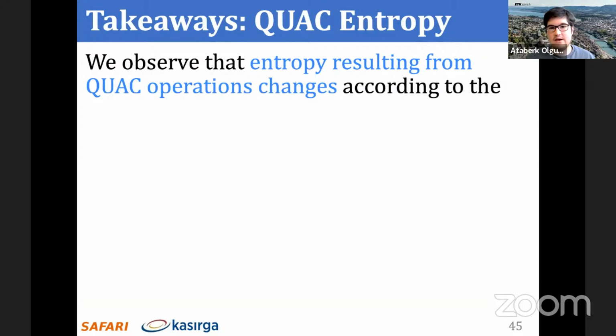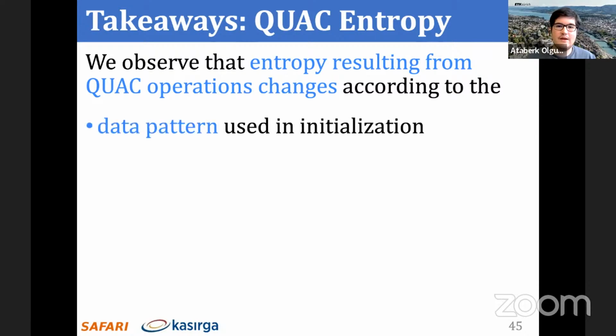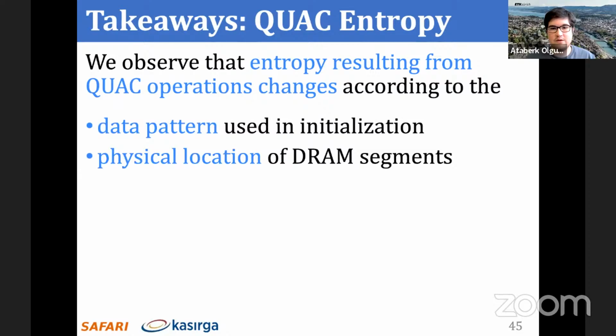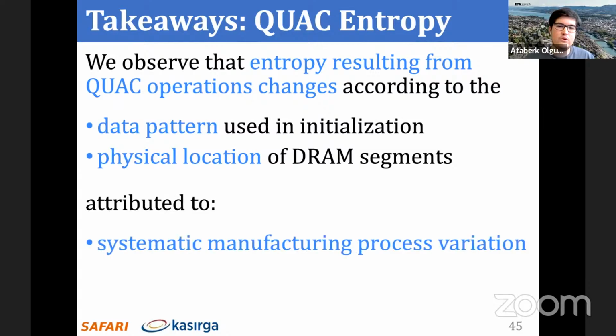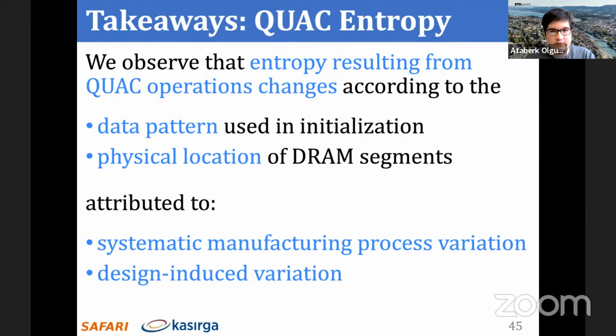And to summarize our analysis, I will provide you with key takeaways from our analysis of entropy. And we see that the segment entropy changes according to both the data patterns used in initializing DRAM segments and the physical location of DRAM segments. So we attribute these to both systematic manufacturing process variation and design-induced variation-related effects.